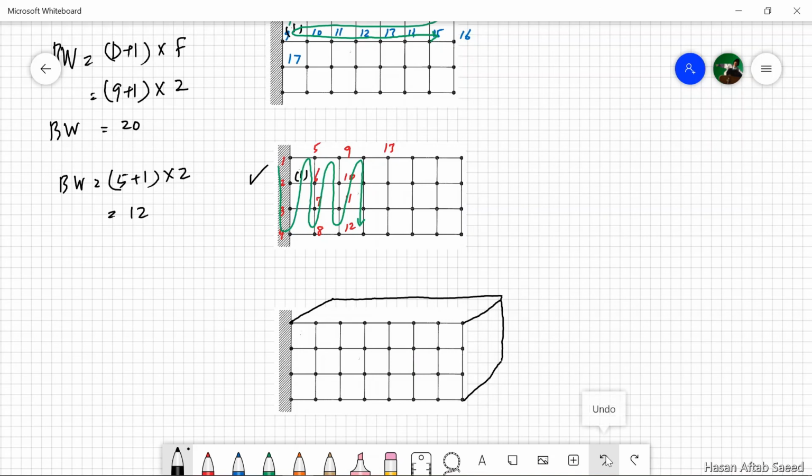And there will be meshing in that direction also, because 3D elements are volume elements and solid elements. The mesh will be something like this. Obviously there will be a mesh like this also. Now you have 3 dimensions. So a little consideration will tell you that you should again exhaust the smaller dimension first, but in this case the smaller dimensions are 2.